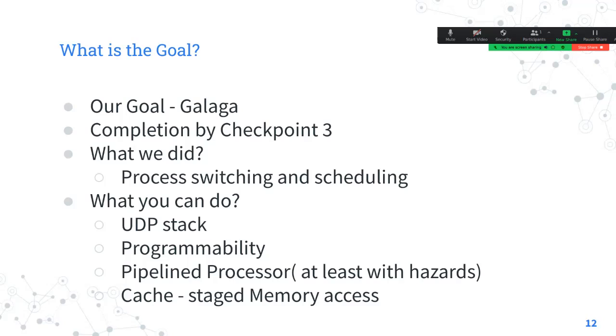If you don't hit in the cache, if it is a miss, then you would have 2 memory clock cycles to fetch from the RAM, in which case you would get the required result at the end of the second stage. So we can use this. It's an additional power consumption because you will be doing both the cache search and the memory search, the RAM search, but the benefit is speed up.